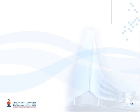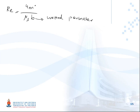So we said that the Reynolds number is equal to 4 m dot over mu b, where b is the wetted perimeter of the condensate.